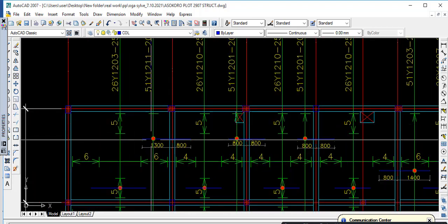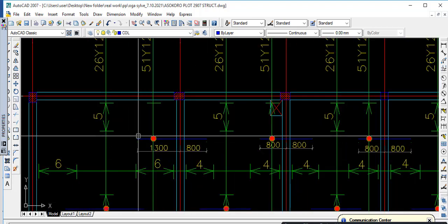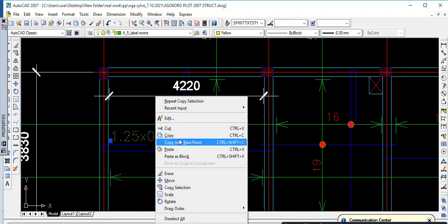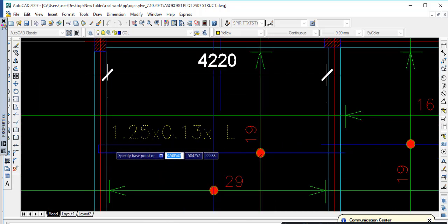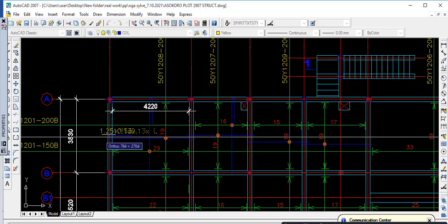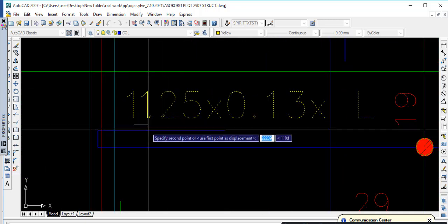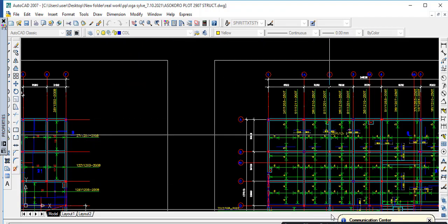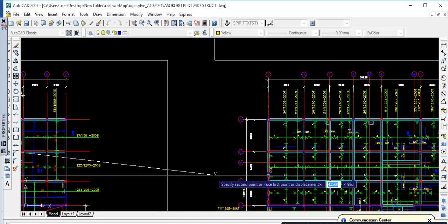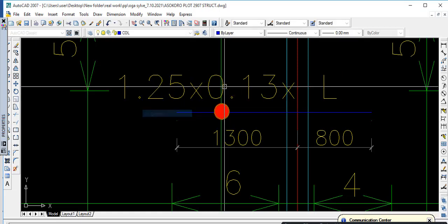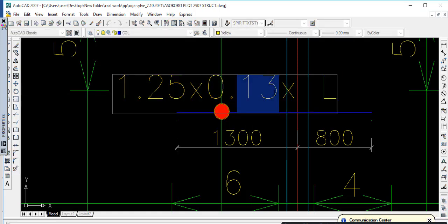And on this part, how this was arrived at, I think I've already explained it. Where the bar, this bar, is returning and is not continuous, you use 0.13. But in a place where it's a continuous bar, instead of 0.13 we use 0.25.